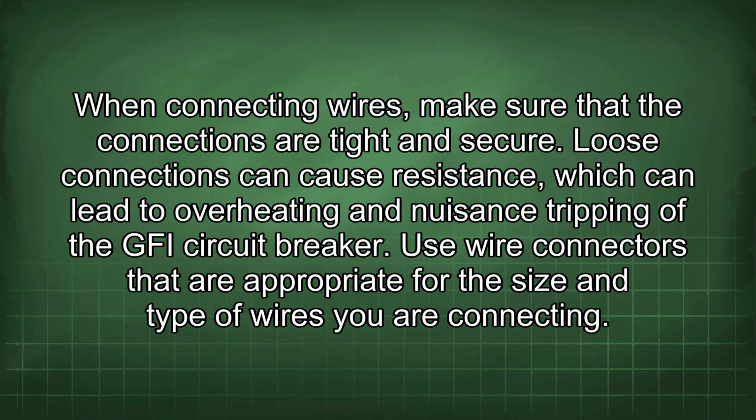When connecting wires, make sure that the connections are tight and secure. Loose connections can cause resistance, which can lead to overheating and nuisance tripping of the GFI circuit breaker. Use wire connectors that are appropriate for the size and type of wires you are connecting.